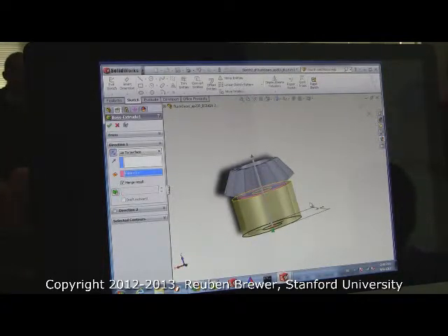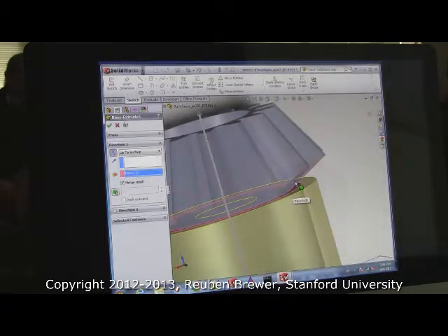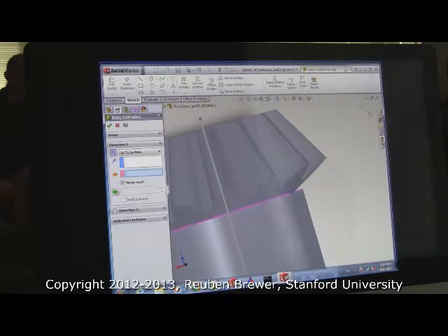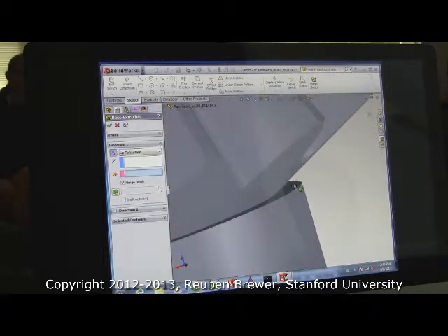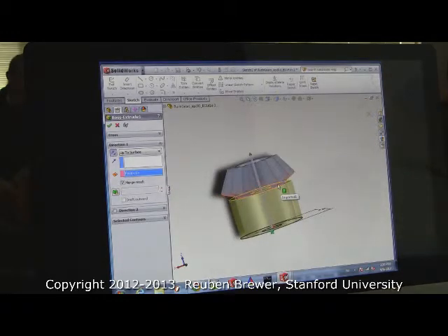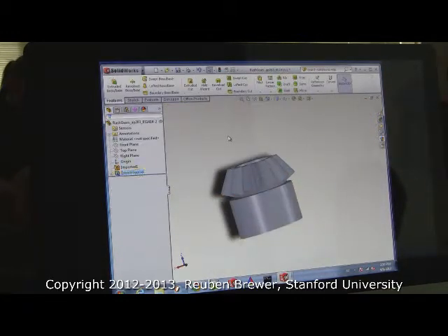And SolidWorks crashes quite commonly when you do something physically impossible. So if you were, say, to click on this surface or this surface by accident because you weren't zoomed in enough, there's a good chance SolidWorks will think for about 10 minutes and then close down. That's why you always want to zoom way in. Okay, so look at your gear. You see that lip right here? Zoom in. It's this ring. And then when you've got that, hit the green check mark.